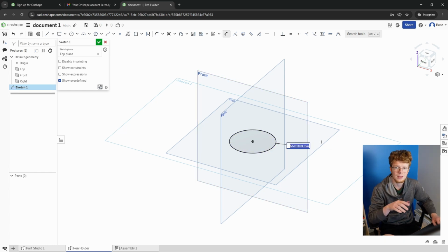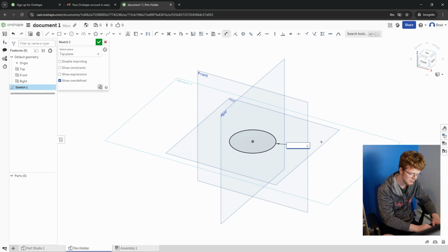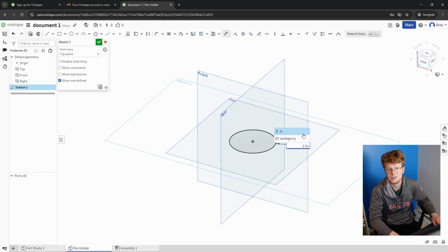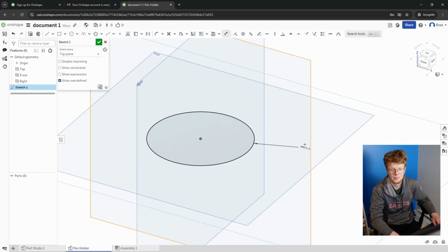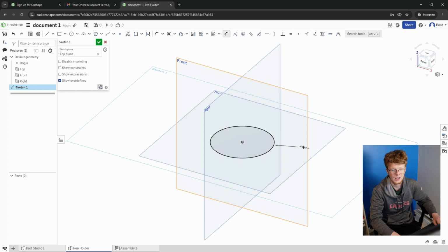What I'm going to do is type in 2.5 inches. So 2.5, and if I type in IN, it's actually going to pop up inches here. So you click on that, and then press enter. And you see that instead of showing just millimeters, it's now inside of inches, although it will display millimeters on the screen. So you can still use inches inside your designs, even if you set it into millimeters. It just translates out into your 3D printing programs a little bit better, and is generally better for smaller designed objects.